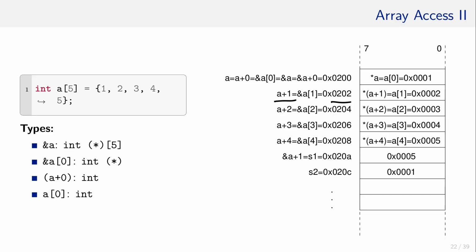If you try it on your PC and you get segmentation faults, that means that the operating system terminated your program because you accessed memory you are not supposed to. In embedded systems without an operating system, you are free to access and mess up everything. Oh, by the way, the addresses that are used here are for demonstration purposes only. Your memory organization might look very different.